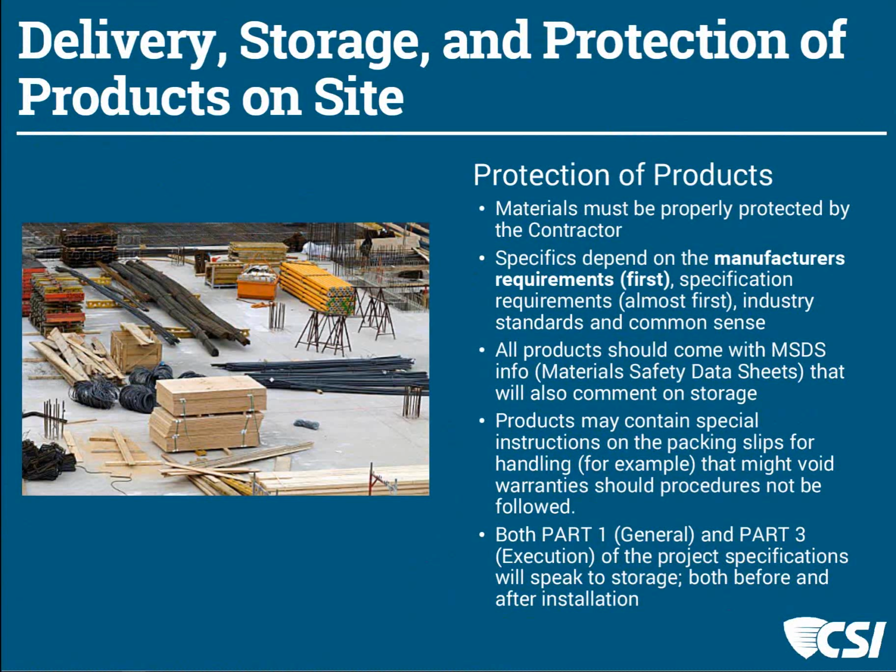Materials storage is something that I find to be lacking, as far as meeting what contract documents require, often. And I see it with products like building felt and blue foam insulation. If we go in and study what the manufacturer suggests for particular materials, for example, there are very definite short time limits for exposure to ultraviolet light and the sun.